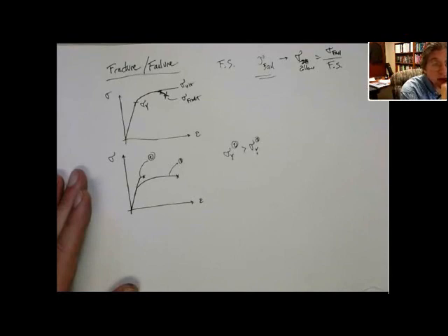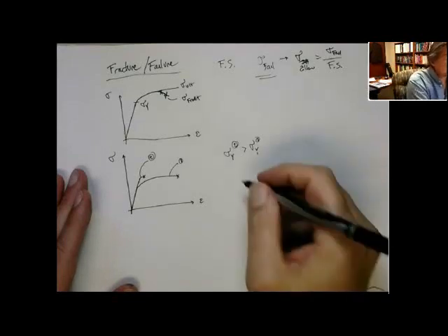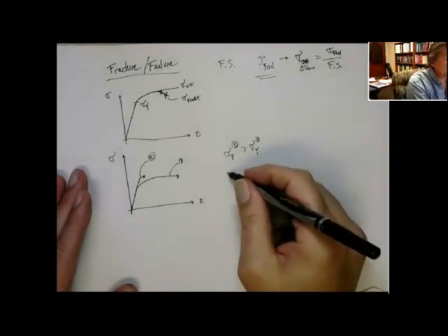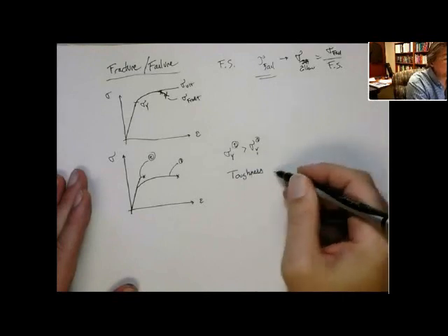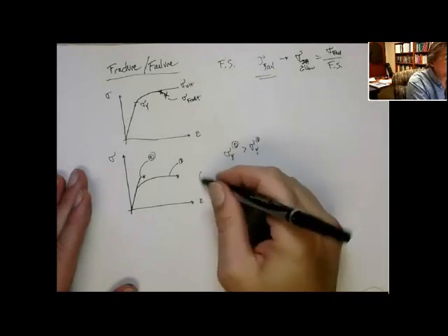The ultimate is higher for material 2 than material 1. So obviously material 2 is better. Well, that's not necessarily true. If you want to look at something like being able to absorb damage, you get quite a different situation. So a lot of times we talk about this notion of material toughness, or sometimes it's also called fracture toughness.